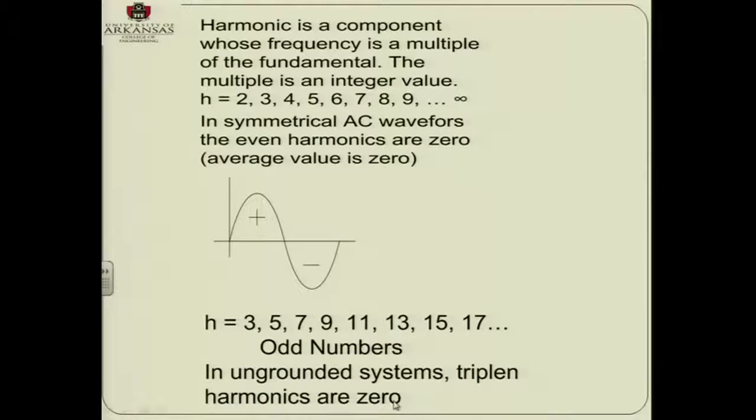So if I'm using a drive, an inverter to control the speed of the motor, like the ones that ABB Baldor produces, I wouldn't expect to see a third harmonic. I wouldn't expect to see a ninth. So in three-phase systems, you only expect to see the 5th, the 7th, the 11th, the 13th, 17th, 19th, and so forth.